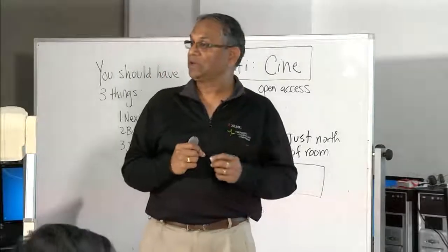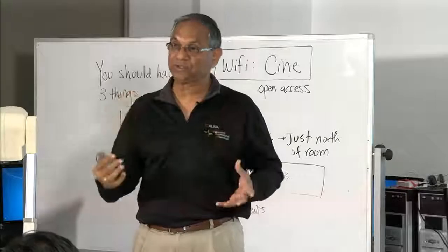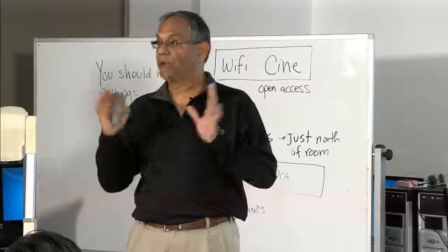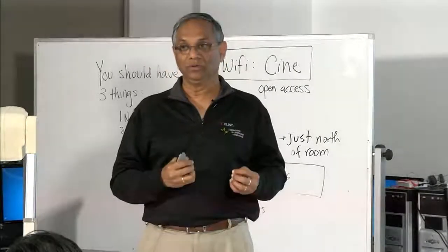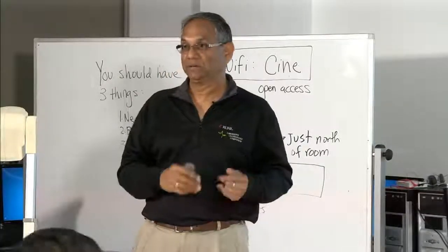It means you will never run out of flip flop resources if you are creating a sequential design. You have plenty of them, and we strongly recommend that you do sequential or synchronous design in FPGAs. Can somebody tell me why not asynchronous design?